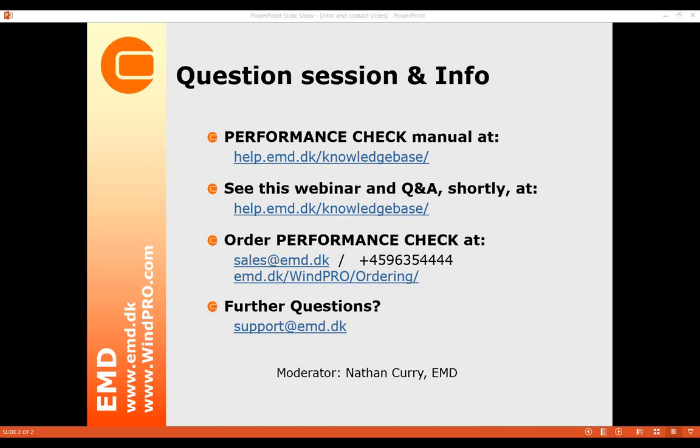In terms of using the performance check module for calculating the wind corrected production, it does of course matter what kind of availability data you put in, and the warranted availability might not be the right one. The best one is the energetic availability, the energy loss when the turbine is down, and not necessarily the warranted one, but the one counting all events, except for the permissible ones, for example, shadow stop and other curtailments, which of course you will never get back.